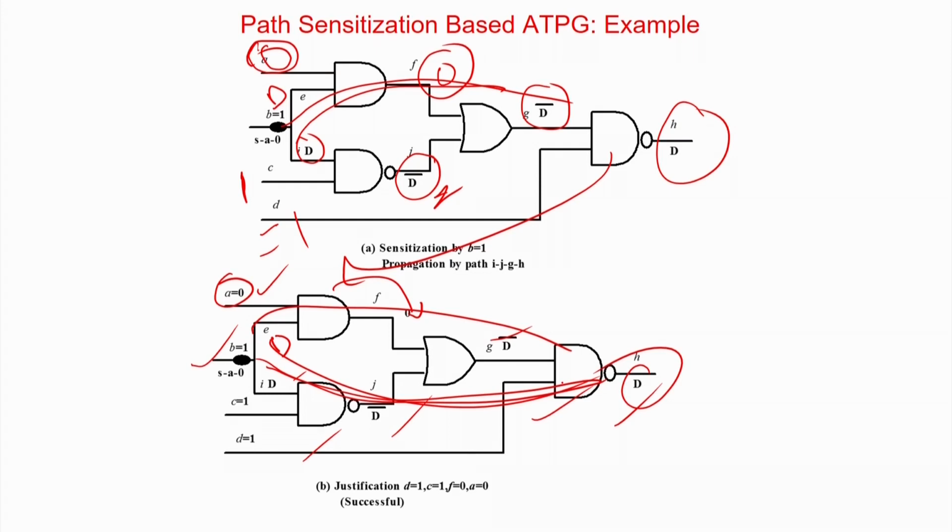So, when the circuit has to be tested, these patterns have to be applied physically, and the golden response in this case is D. In the previous case, whatever the golden response means is the expected response that the test pattern applied to the circuit will give you, and that has to be matched in physical testing, and if it is proper, the circuit is correct, else there is a fault. So, with this we come to the end of automatic test pattern generation for combinational circuits. In the next class we will see how things start becoming complex if there are sequential elements in this. Thank you.